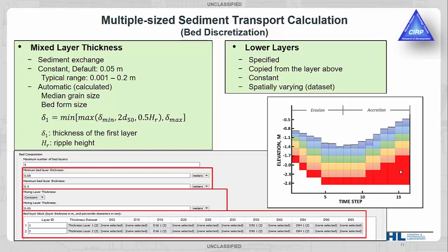When you specify layer thickness, you can specify each layer thickness, but you can also specify just a few layers you picked. If you specify layer 1 and 2, in our case, you see that in the interface window below. So we have thickness layer 1 and thickness layer 2. We specify layer thickness in these two data sets. Layers 3, 4, and 5 we didn't specify.